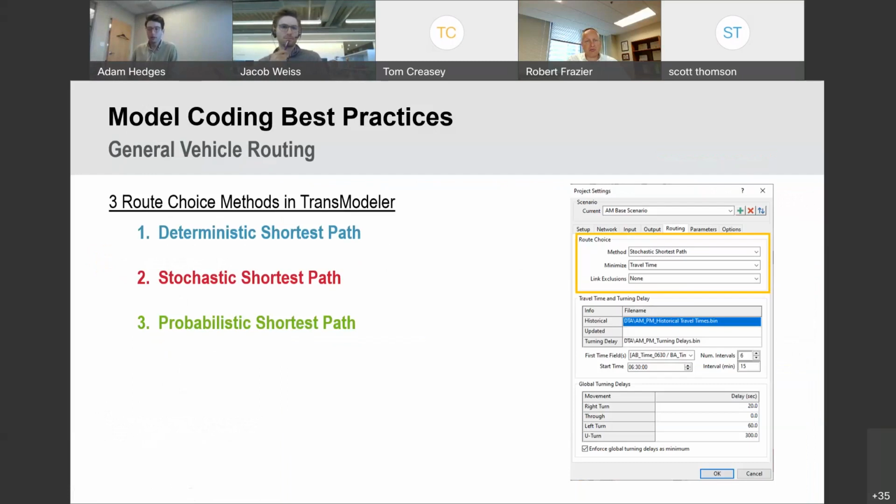So you don't have to specify that somebody needs to go right here through the next two intersections and then turn left. TransModeler will just identify, based on the network, what the possible routes are between all the combinations. So it's using the physical network and then those origin and destination points to establish those routes.